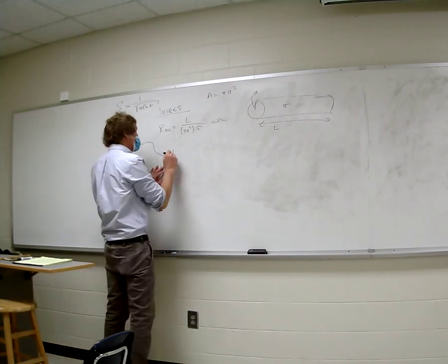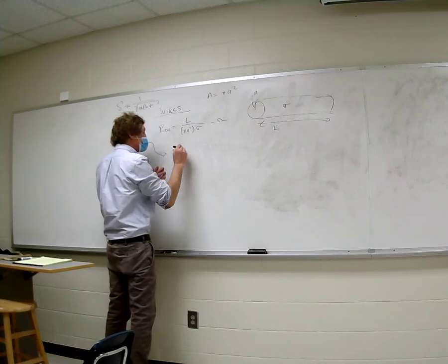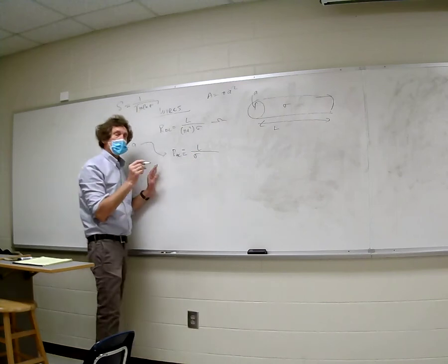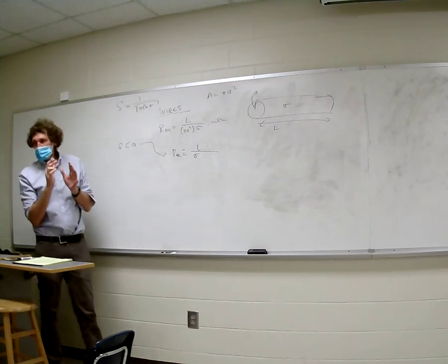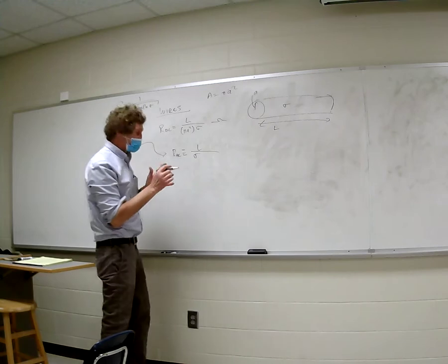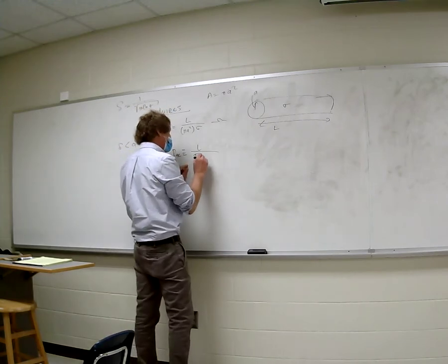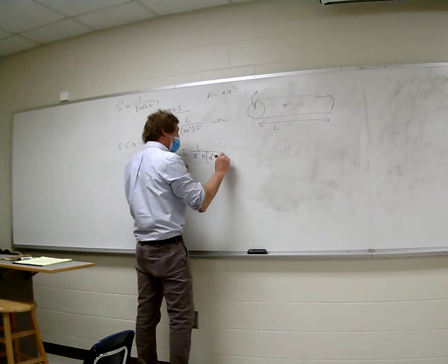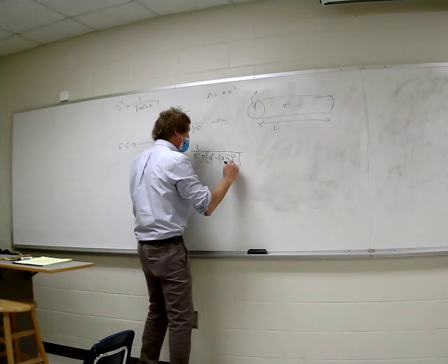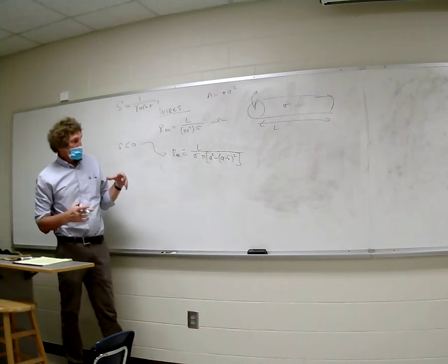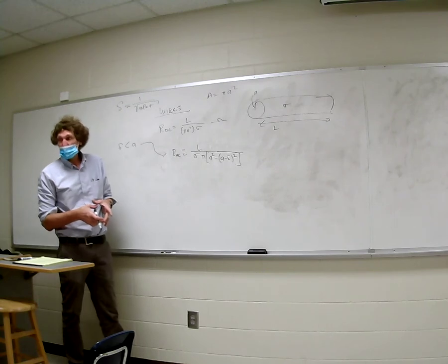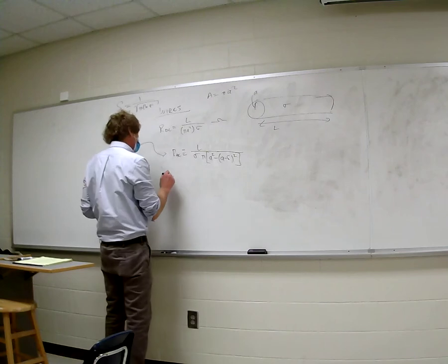Then you have to put down R AC. This is an approximation. It's still proportional to the length, inversely proportional to sigma, but now the area changes. Technically what they'll put down, and you don't have to do this, if this is the case, you'd put down pi times quantity A squared minus A minus the skin depth squared. The pi A squared is just the area. The pi times A minus the skin depth squared is really the area of the core beneath the skin depth that you're subtracting from.